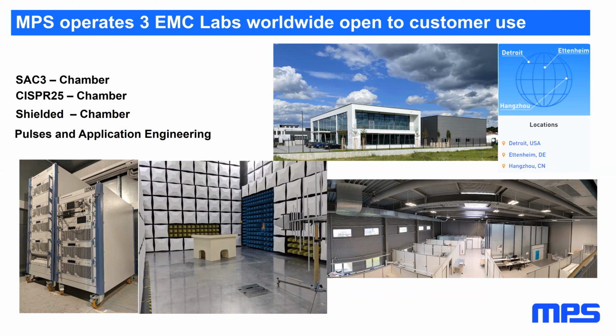Now we have, how do you avoid the audible noise being generated when using the spread spectrum? Normally FM means I have constant output energy. So I can only hear audible noise if I really have power changes, which means I have some sort of AM content.